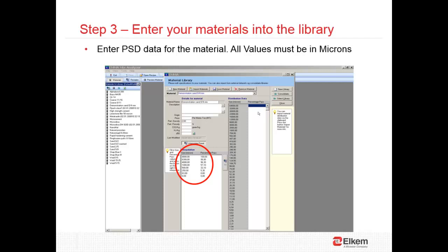Please note the sieve sizes must be in micron and the grading data must be as percentage passing figures. EMMA recognizes the maths symbol version of your computer's operating system. Therefore, if you're using the continental comma for a decimal point, please continue in this format.